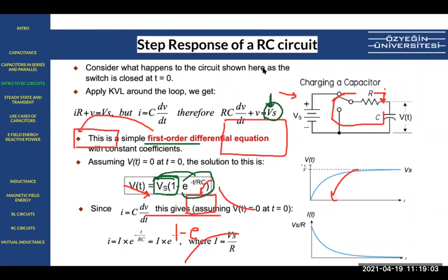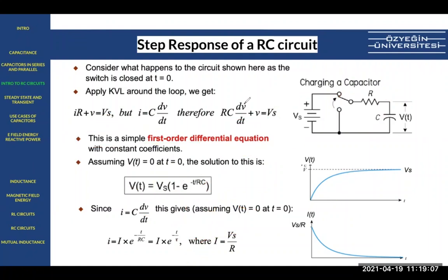Okay, so quickly you can make a check. What if I put Vs instead of the V? What is the derivative of Vs with respect to time? Vs is a fixed voltage. We have this Vs voltage, so I'm just quickly trying to find the solution of this first order differential equation. Our variable is the voltage on the cap, and we found the nodal equation, we put in the characteristic equation, so we have this equation. So quickly trying to find the forcing function solution.